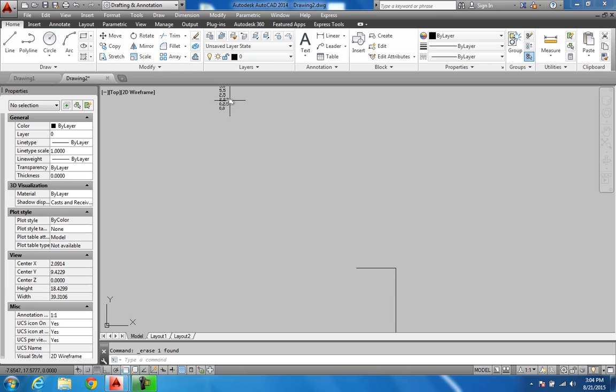Now, I want to start back at this point right here. Now, I could go up here and find that Cartesian coordinate of it, or the absolute coordinate of it, or I can just snap. Come up here and hit line, and with this object snap on, I can catch that point and take right back off. And x was 2.5, comma 2.5, enter. And I messed up again, so escape it a couple times.